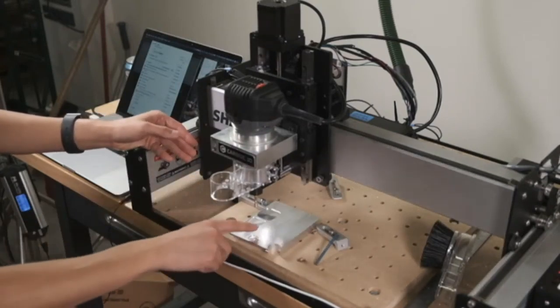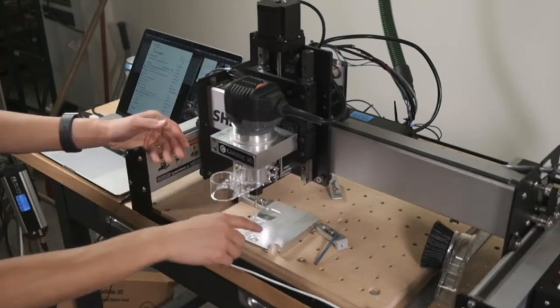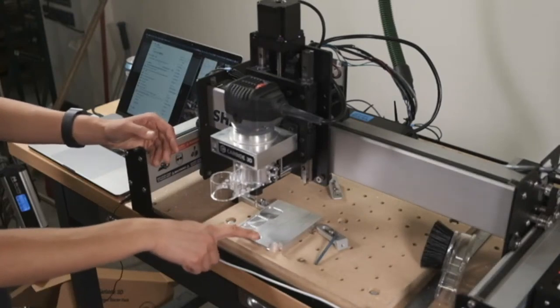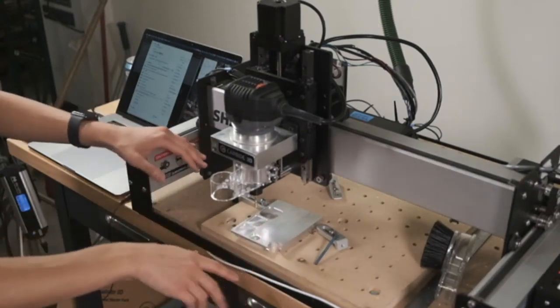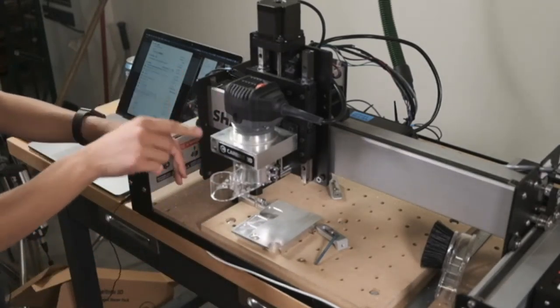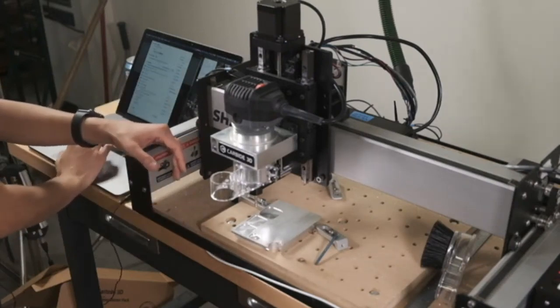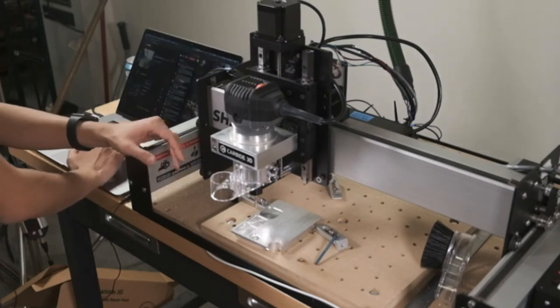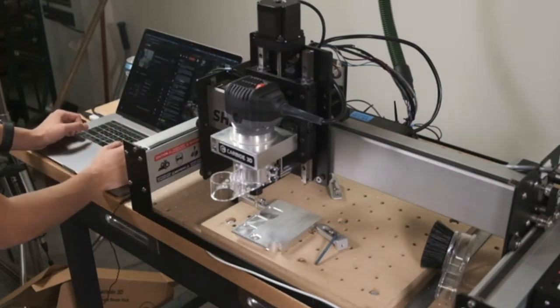So you can work out maybe a shallow enough cut that you're putting less energy into your part. But if you have a large enough piece that will dissipate the heat at the rate that you're putting energy into it with your router, you should be okay. We talked about the sound of a cut, and that is everything on my agenda. So I'm going to open up the chat, and let me know if you guys have any other questions.